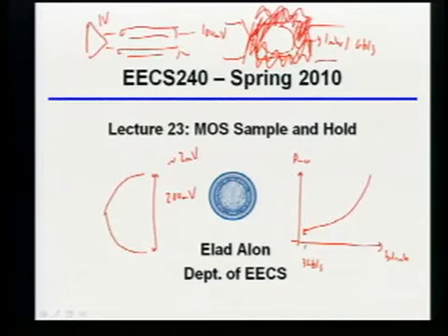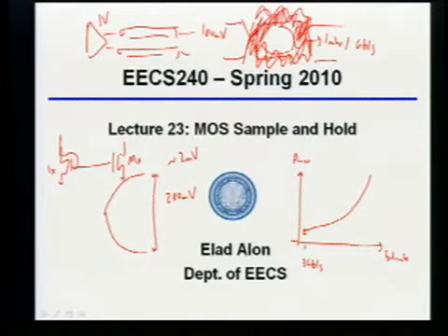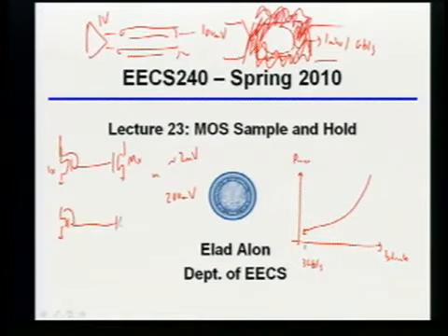When you say different width, you just mean effectively different multipliers? Yeah. Well, that's a good question. So if you have something like this, and let's say this is a 1x and this is an mx, right? You can always think of this conceptually as if I've really got one transistor over here, and there's another transistor over there. So let's say that these were both effectively 1x. That you certainly know how to do, right? Essentially we said that the offset between them was using that AVT that I had given you, right?